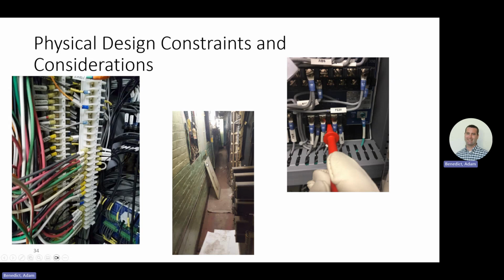Same thing here. This is a station that I worked on where I had to turn sideways to walk down here. So this is not ideal when you're trying to install a new relay or do any design if you have to turn sideways to walk down there. So this station actually was getting demoed and a new one was getting installed. So that was lucky, but sometimes they try and reuse these as best they can to limit costs. And then this is just showing, make sure to consider physical access when it comes to testing.